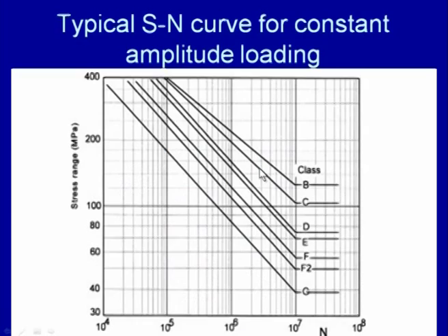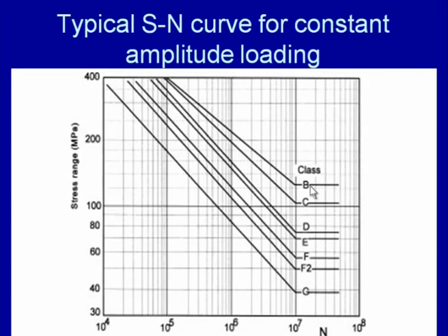So, that is what we will be looking at in the subsequent slides, but the important thing is that based on the type of the loading, the type of the weld joint, and the possibility of the failure by cracking of the weld, and the kind of the joint, whether it is partial penetration or the full penetration, the given weld joint is categorized into the different classes.